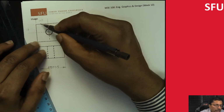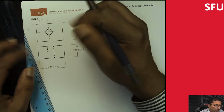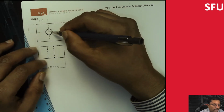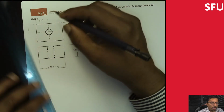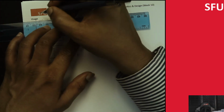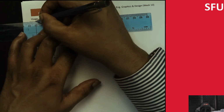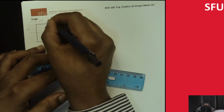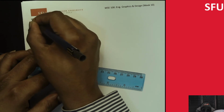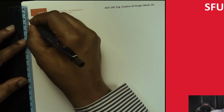For this one, I haven't actually put tolerance as of yet. The reason is we are going to specify the true position of the hole here, right? So we shouldn't put the tolerance over here. Maybe I need the arrows on the outside, and probably arrows on the outside here as well.